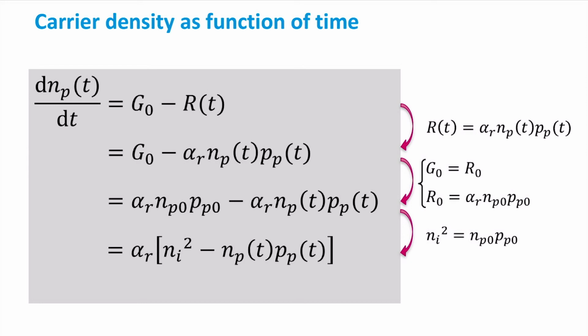We now arrive at the differential equation with time-dependent electron and hole concentrations. At this point, we cannot solve this, and therefore we apply the condition of low-level injection.